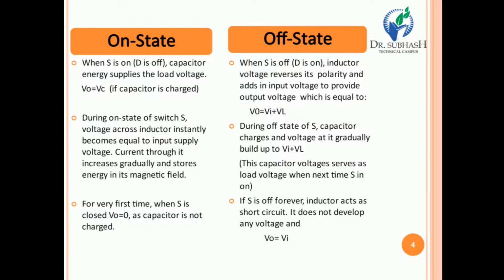So, dear students, now we can be clear about the output voltage. In the on state, the output voltage is equal to Vc, the voltage across the capacitor, and in the off state the output voltage is equal to Vi plus VL.